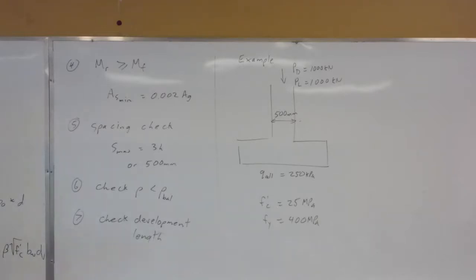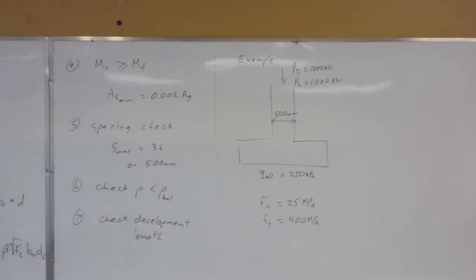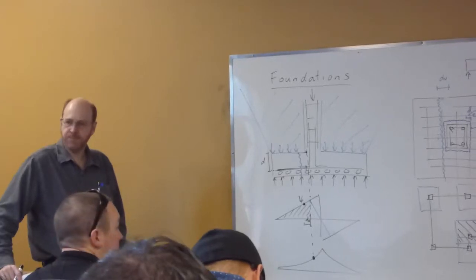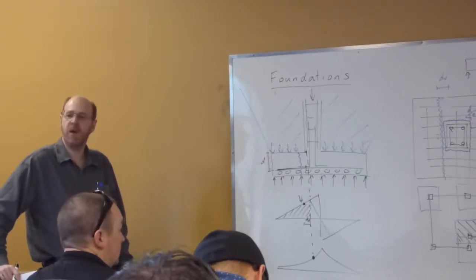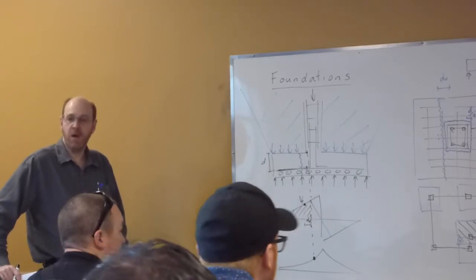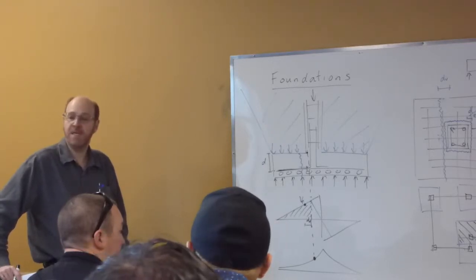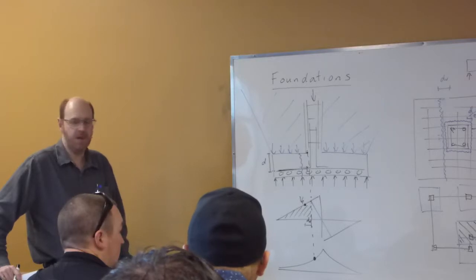Also, what's quite common with a footing is to use 25 MPa concrete. Even though you might use 35 MPa concrete for the rest of the structure, the footing is often using a lower quality concrete. And the reason for this is cost. Now, when we get into our calculations, we end up with a relatively large footing. Again, this is based on not exceeding the allowable bearing pressure of the soil. So what that means is a fairly large volume of concrete. And then because we want to avoid shear, we end up putting in something that's fairly deep as well.